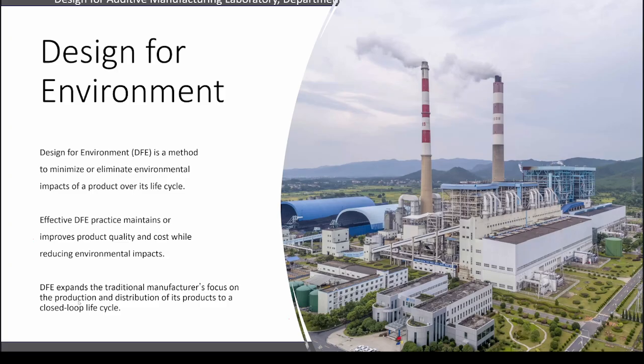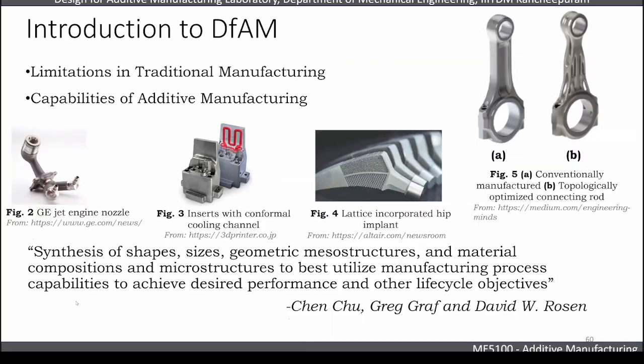Right. So with that, I think DFAM, or design for eco design, we start first with an introduction to DFAM. DFAM means design for additive manufacturing. When the design is suitable, you are talking about design freedom. Design freedom is available in so many different ways. For example, here the part consolidation, and then increased complexity in the cooling channels, and then having mesoscale, microscale structures